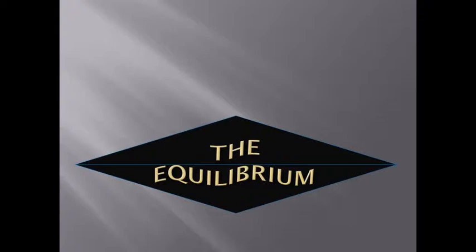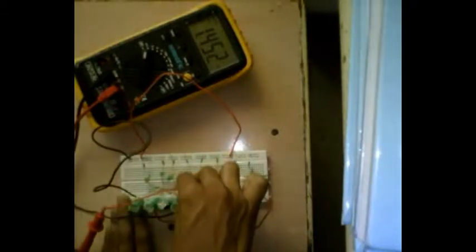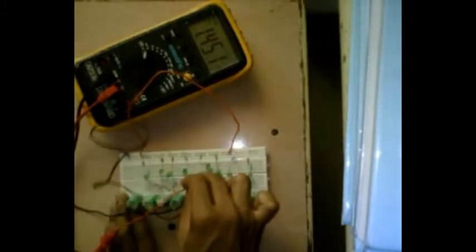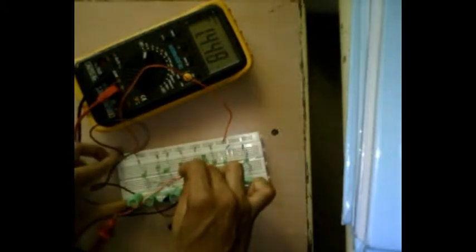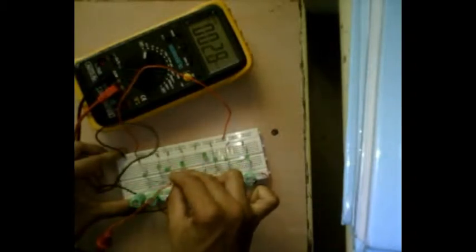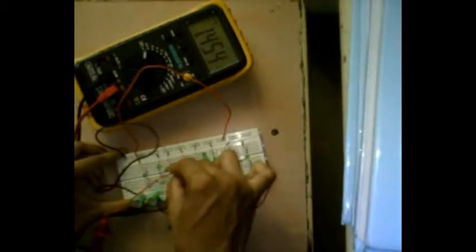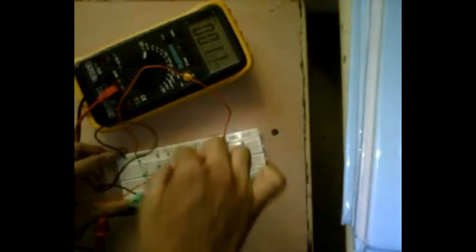How long does this process take? I used a multimeter connected across all the capacitors, and I observed that even after the LEDs stop glowing, there is still a change in voltage in the circuit. Equilibrium is obtained in all the capacitors when the reading in each of them was about 1.4 volts. It did not become zero. There is still a reduction, but the rate is very slow.